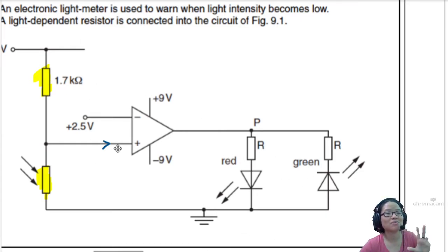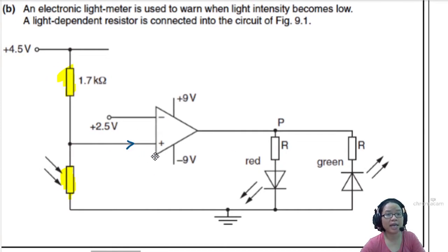So the ideal op-amp is one that doesn't affect the output and doesn't affect the input, but it must have different properties at output and input. For the input, it should have infinite resistance. For the output, it should have zero resistance. But you cannot use the word resistance because this is not necessarily a direct current circuit.